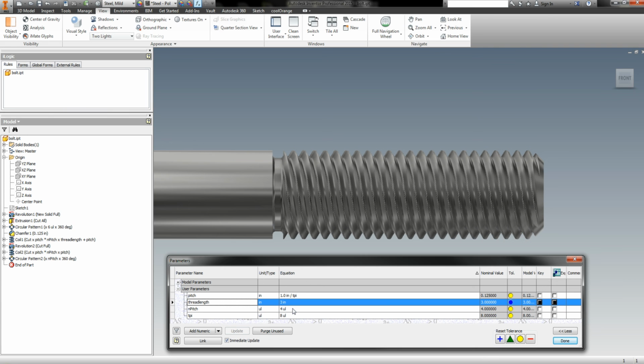But if you're going to use these for 3D printing and you actually want to be able to thread something onto here, you can follow the same process, but whatever your thread profile is, you wouldn't follow it exactly. You got to make it a little bit bigger. You have to cut away a little more material, maybe 5% more or something like that. You'd probably have to print it and try it.